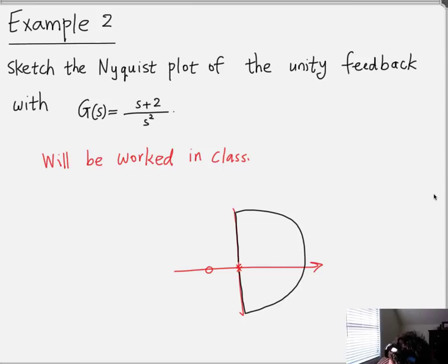You have to bypass the j omega axis poles or zero, so in this case my contour A is going to look like this. And of course, remember that your contour A will always have to move clockwise. Okay, so this is going to be an example that I'm going to do in class. Some details are going to follow during the class.